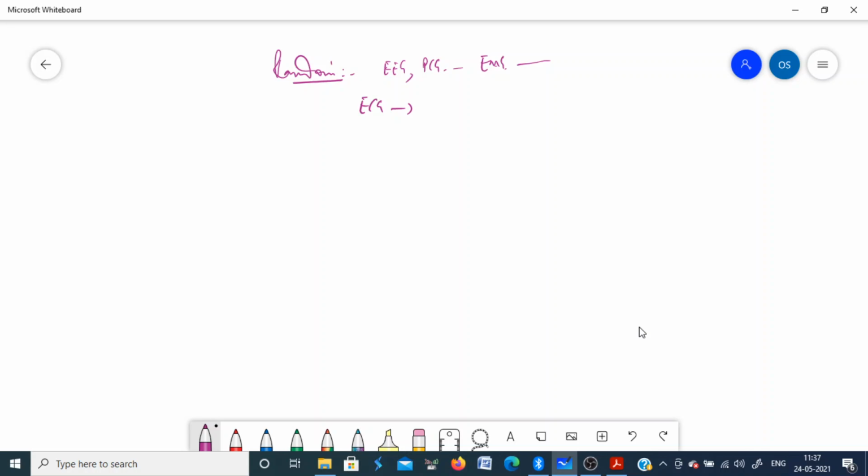Now, as far as random noise is concerned, if ECG is mixed with EMG, the noise that I am trying to remove is EMG, which is basically random noise. If ECG gets corrupted with 50 Hz noise, the noise that I am trying to remove from the signal is now a structured noise, a periodic interference in fact.